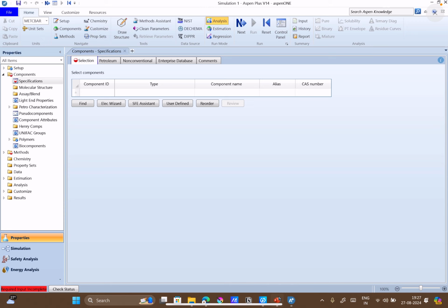Okay, so now here we have selected 3 components and we have provided vapor liquid equilibrium. Now the number of tie lines you can change from 5 to let's say 10, so we might have more data points. Okay, and run the analysis. Yeah, so these are the tie lines, the ternary diagram. This is how it will look. Can you move the legend to the right?